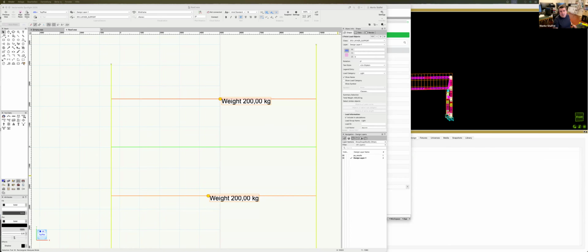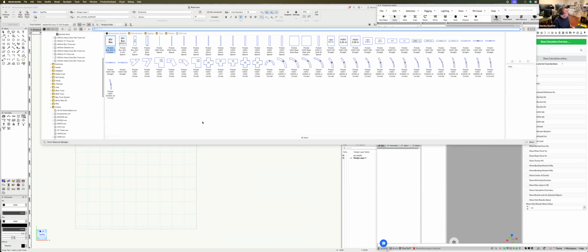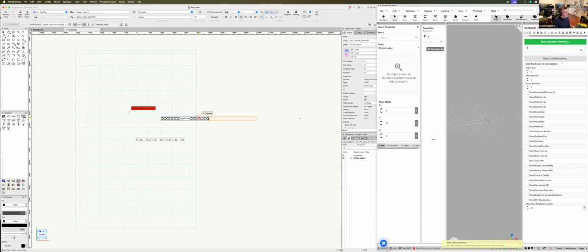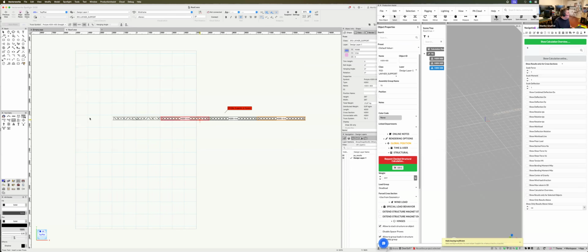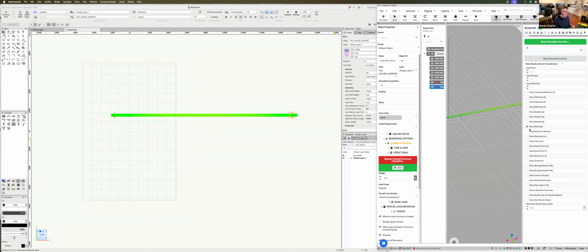This is the display of deflection limits. By default, when you're inserting a truss here, they don't have deflection limits. So for example, if you have a European truss, I make this extra long, and I add some fixtures, some hoists here, you will see that the workload of the truss is actually 23%. So it's totally doable to have such a long span.